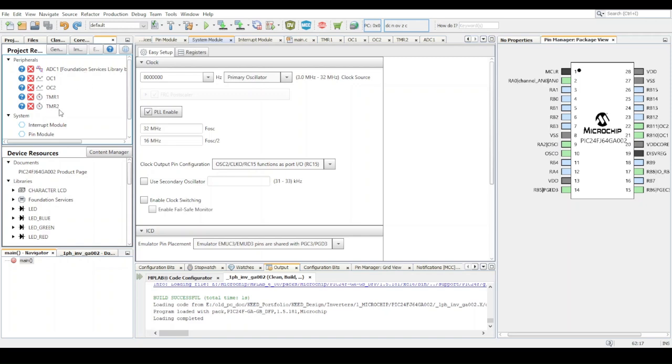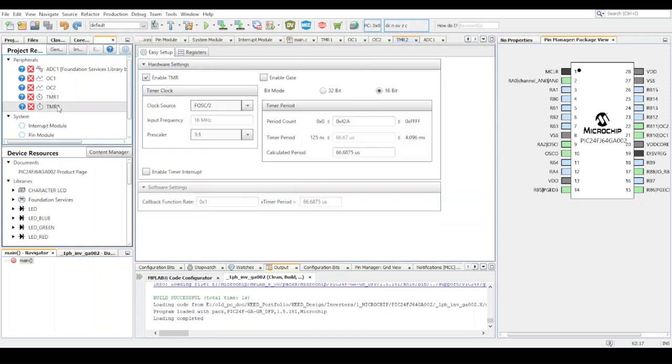If we take a look at the PWM peripheral, we go over to timer 2. It's important to note that in this case, the switching frequency is selected to be 15 kilohertz. Typically with the inverter, you could go up to 20 kilohertz. Well, you could actually go as high as you want, but typically you keep it around 15. An advantage of this is great PWM resolution, in terms of the variations of duty cycle you could do.